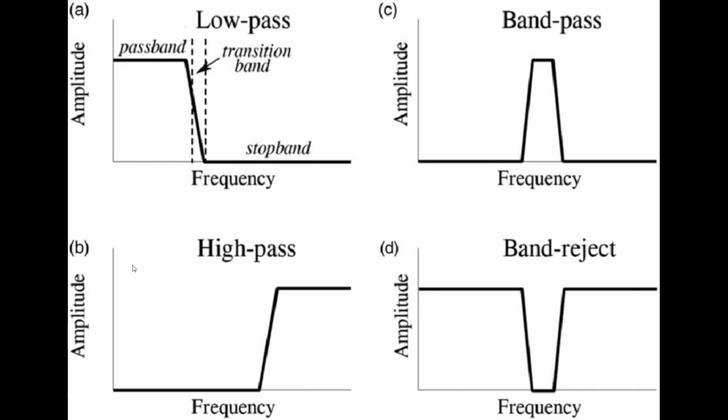The filters are applied by manipulating the frequency domain representation of the signal after the discrete Fourier transform. Now, for the implementation of different types of filters in the frequency domain, the following steps are taken. For a low-pass filter, the frequency components with frequencies higher than the cutoff frequency are set to 0. This is done by checking the magnitude of each frequency component and setting those above the cutoff to 0.